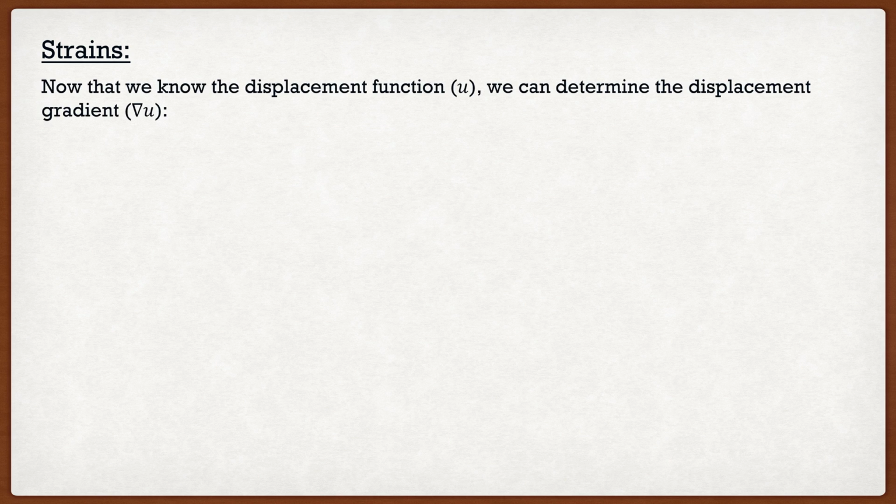Well, we get displacement functions in order to find strains. So now that we know our displacement function, we can start to find the strains. But the step that we have to do before that is finding that displacement gradient, nabla-u.